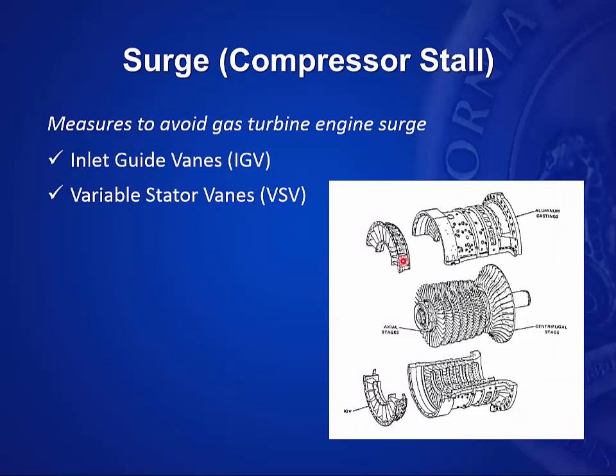The inlet guide vanes, this ring right in the front, and it's in two halves, an upper and a lower section. And if you look carefully, there is a control arm here that when activated, and all of these would turn at the same time, would rotate these blades, and then the air passing through that blade, as I'm rotating it, will change the angle that it exits the inlet guide vane. And then that is going to strike your compressor blades.